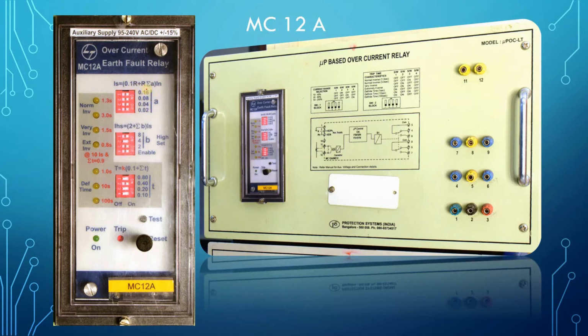And IN means that is the rating of the relay. IN also signifies current rating. Like in the earlier case, the CT secondary is nothing but the current rating. Similarly, here IN is nothing but the current rating of the relay. And in this case, the relay we are using has IN equal to 1 ampere, because the current rating of the relay is 1 ampere. So we have to apply 1 ampere here.